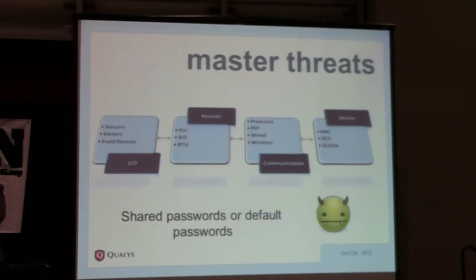If these passwords are not set, if I'm an attacker, if I'm writing a malware like Stuxnet, what will I do? First thing, I will say, oh, is this a system from XYZ vendor? Yes. What is the second thing I would do? Test if it still has the default password, because the password is already in the manual, it's on the internet, that this system from XYZ company comes with this default password. So I'll just try that password. So basic things like passwords and default passwords are still an issue when it comes to SCADA systems. There is no password change policy either.